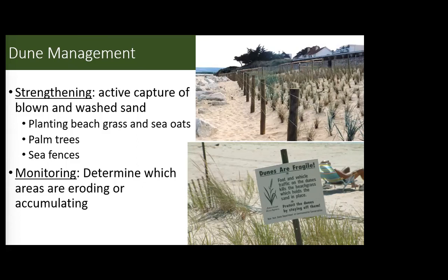So what this actually is, whenever you plant vegetation, all vegetation has root systems. And depending on those root systems, those act as anchors to the sediment. So whenever we're trying to fix stream channels, we build what's called riparian buffers. You'll see in streams that are being really rehabilitated, maybe there was like just a straight course.